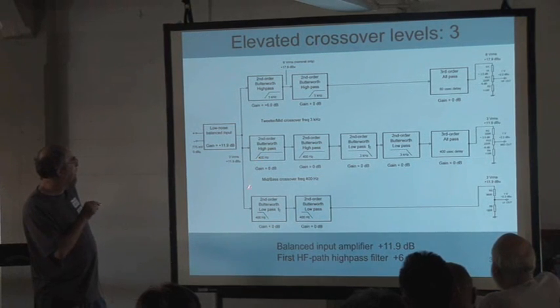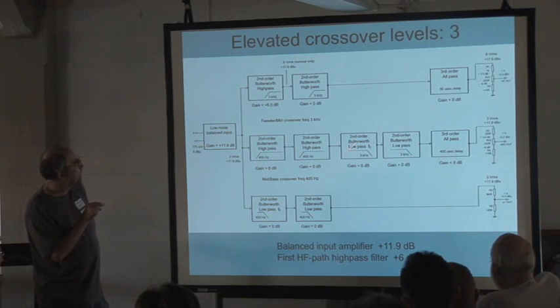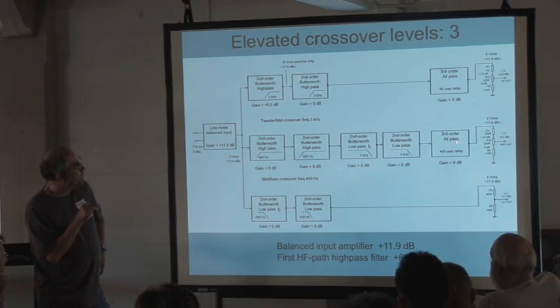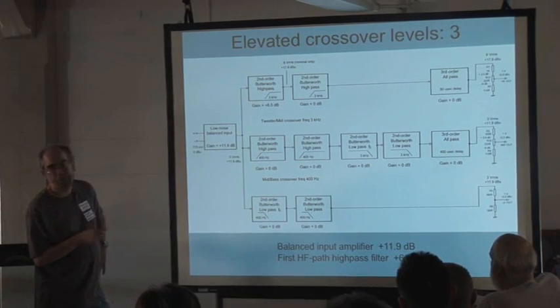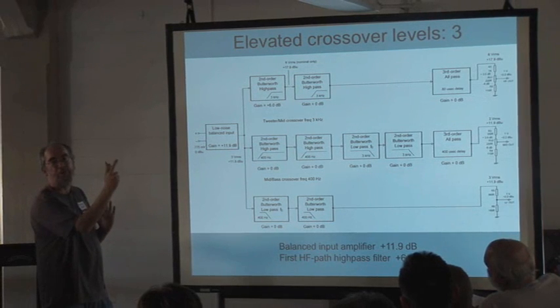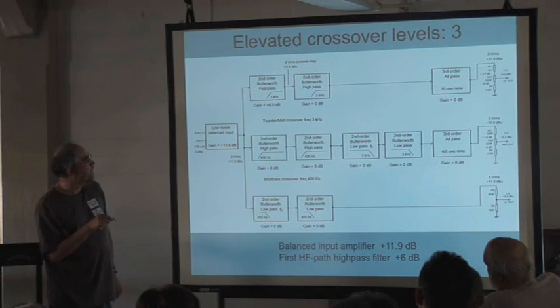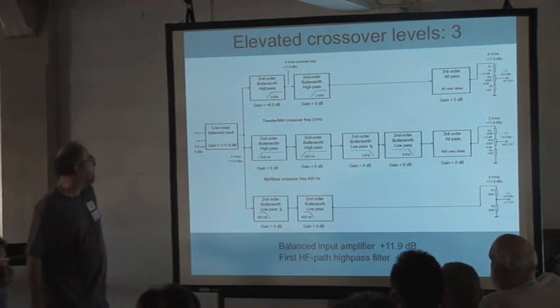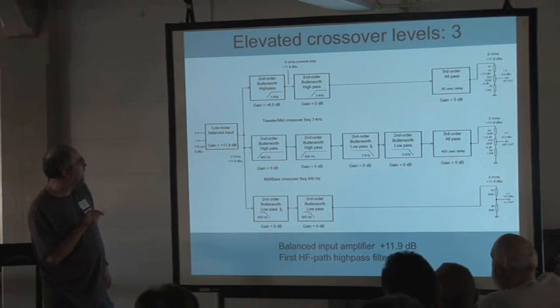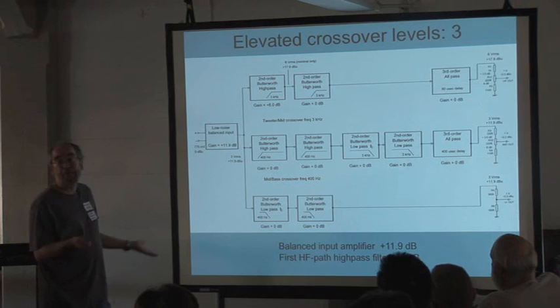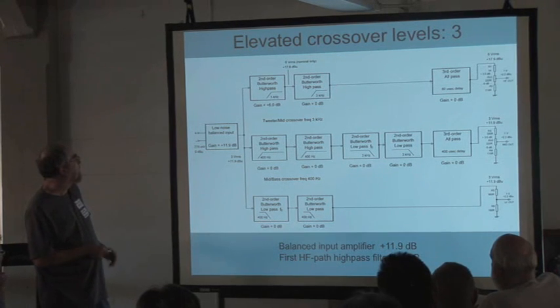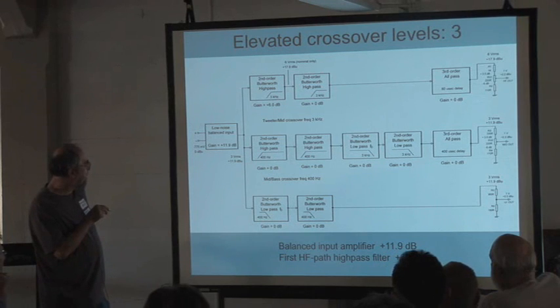Fine, thanks. In the mid path, of course, you've got 2 sets of filters. You've got 2 high pass Butterworth filters, and 2 low pass Butterworth filters. These all have a gain of 0 dBs. You then have your 3rd order time delay filter. That is a 400 microsecond delay instead of 80, because the assumption is you've got a bigger spatial difference between the mid acoustic center and the acoustic center of the bass unit. I'm not sure quite how many millimeters I assumed, but I worked it out carefully, so it came out at exactly 400 microseconds for this example. So the crossover frequencies are 3K and 400 hertz, which are just average values, I would say. There's nothing actually magical about them. Right, and now there's your low pass.